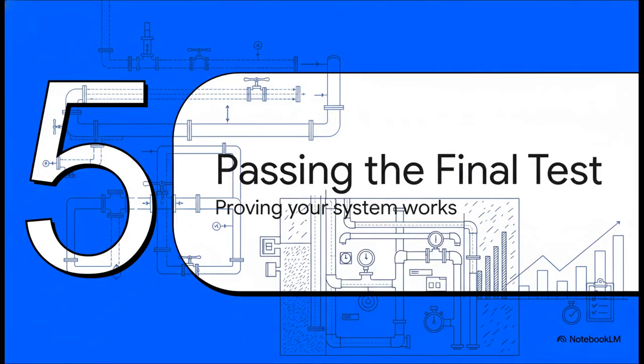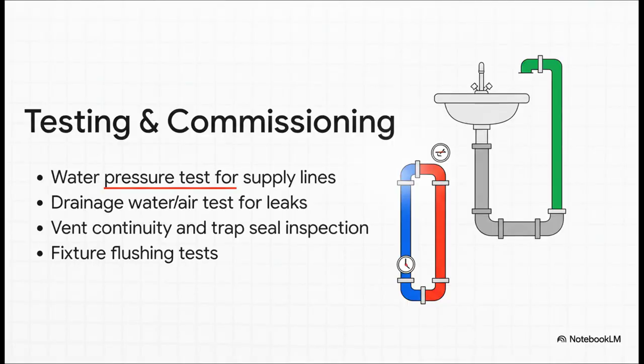So, the whole system is installed. It looks great, but looking good isn't enough. Now comes the moment of truth. We have to put this system through its paces and prove with cold, hard data that it works exactly the way it was designed to. This is basically the final exam. We're going to pump up those water supply lines to 1.5 times their normal working pressure, and then we're going to watch that gauge. It cannot move, not even a tiny bit.